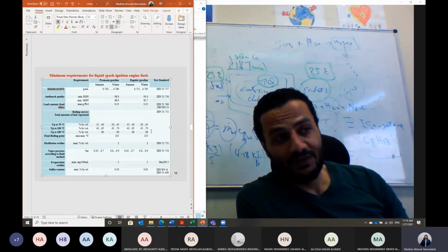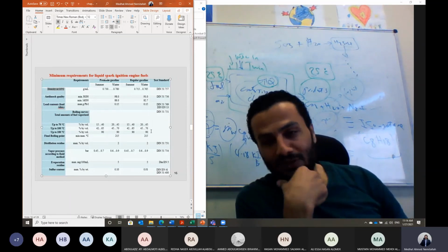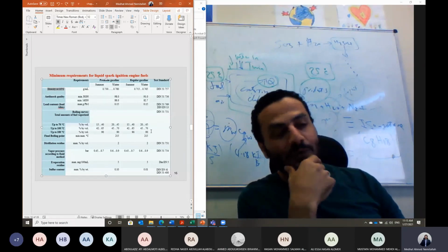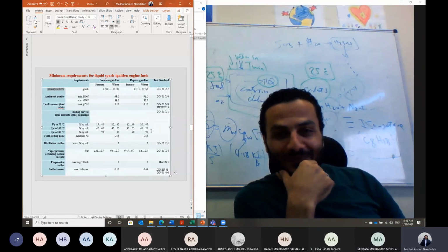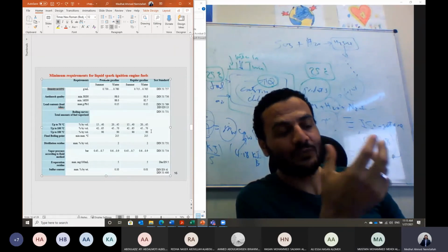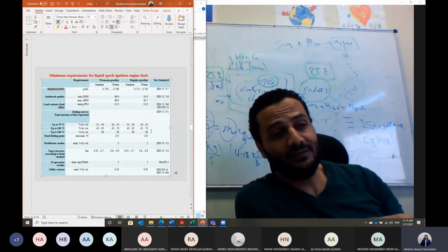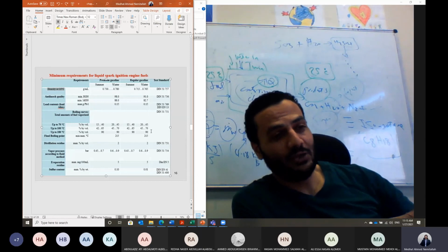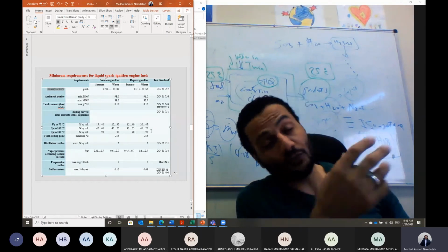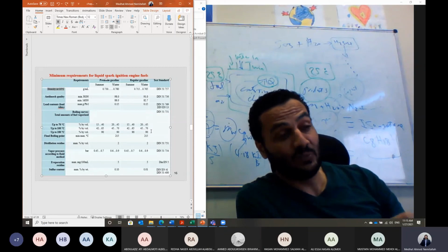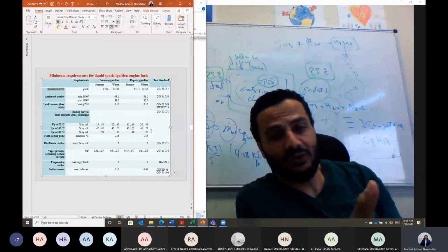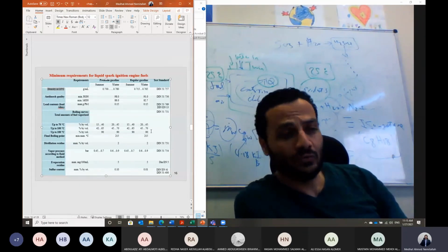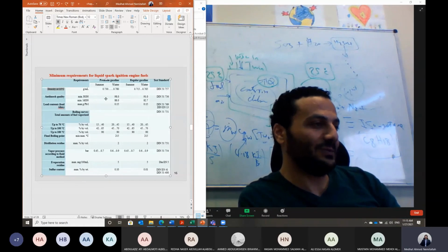Do you need 95? So don't just go to the gas station. I will talk about this inshallah next time. When you go to the gas station, you just find 95 looks red and that looks better fuel. Why not go for 95? So this is something that we'll be talking about. Is it actually, do I need it? For my car, it is better actually to take 80 gasoline, but this is for the old virgin car, octane number of 80, very small octane number. But the car is old and it already does not have efficient combustion or high pressure combustion. So lower octane number will do the job in this case. So inshallah, we'll be talking about this next time.